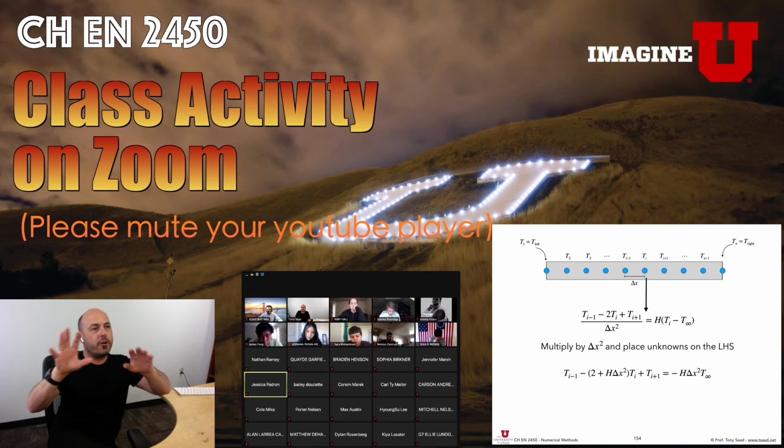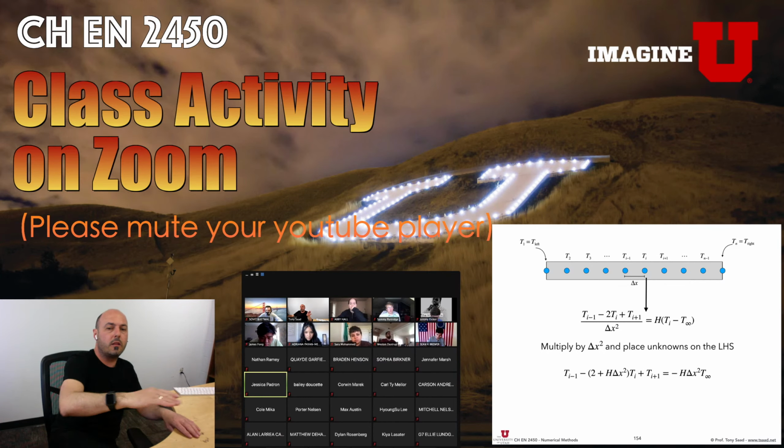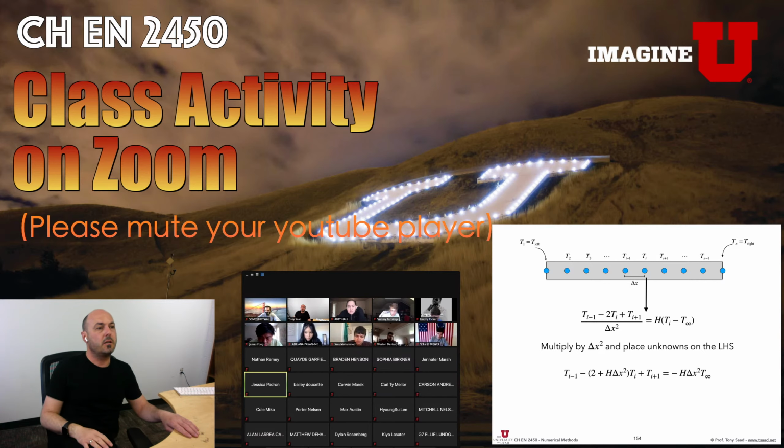Now if you rearrange things a little bit, following the strategy we followed for systems of equations, you put all the unknowns on the left-hand side and everything that you know on the right-hand side, you get this beautiful formula: Ti minus 1 minus (2 plus h delta x squared) times Ti plus Ti plus 1 equals minus h delta x squared times T infinity. Now this is the discrete governing equation at each and every point inside the entire domain.